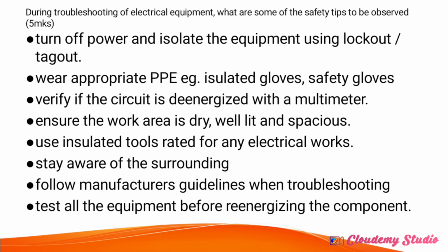Then use insulated tools rated for electrical works. Of course, if you are an electrical person, you have the knowledge of the types of faults that can occur in any electrical installation circuit. So whatever tools you're using, make sure that they are well insulated, so that you can prevent your body from coming into contact with a live conductor or a live circuit.